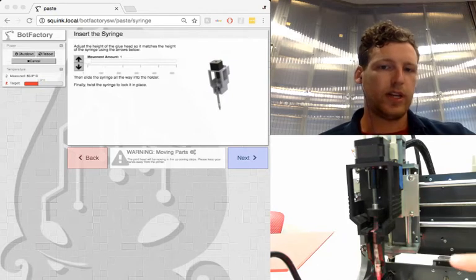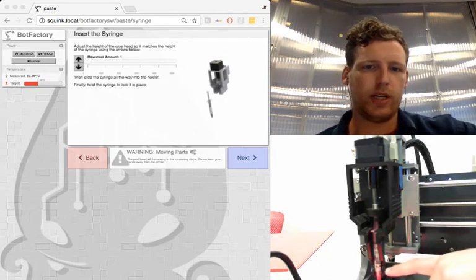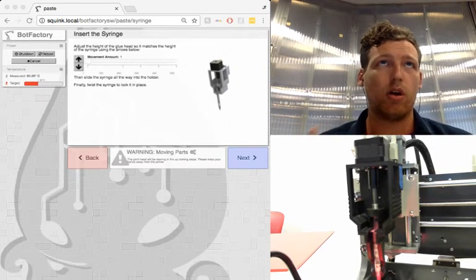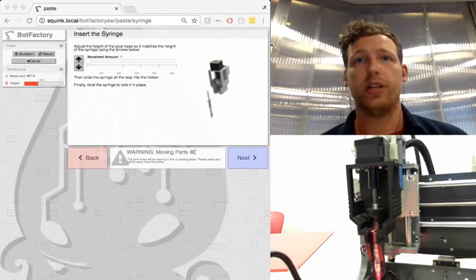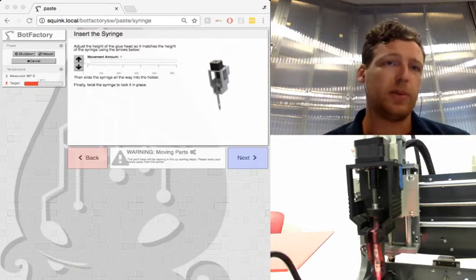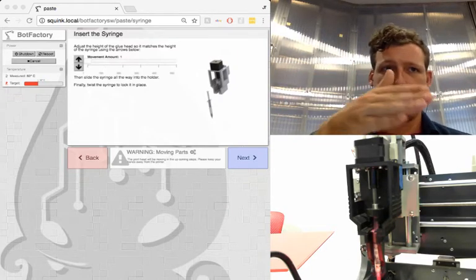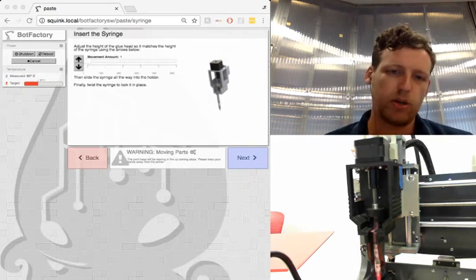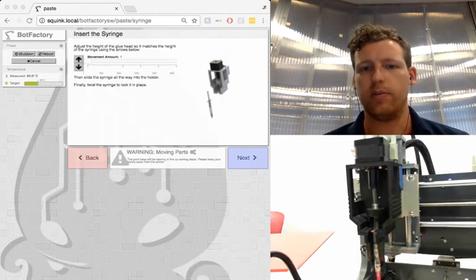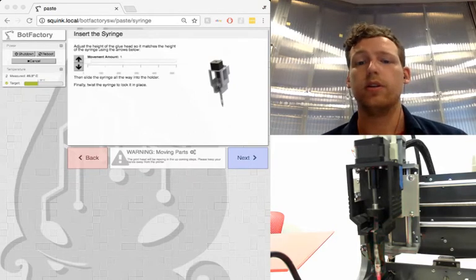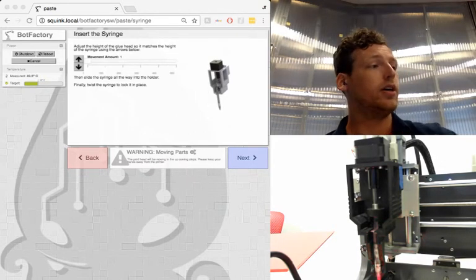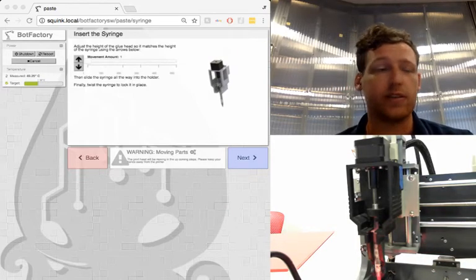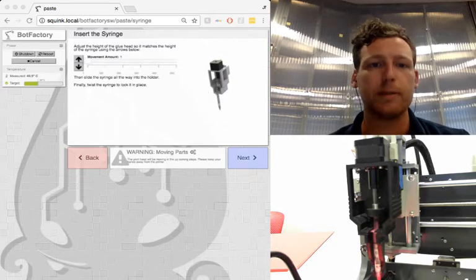This is a new type of head that we've changed. We have included a support structure here to better stabilize it when you're dispensing longer, larger PCBs. We find that the syringe tends to move a little bit because of the pressure applied. So if you're having issues, give us a call and we'll see what we can do for you. This has been an improvement for special cases that you may also be coming across.